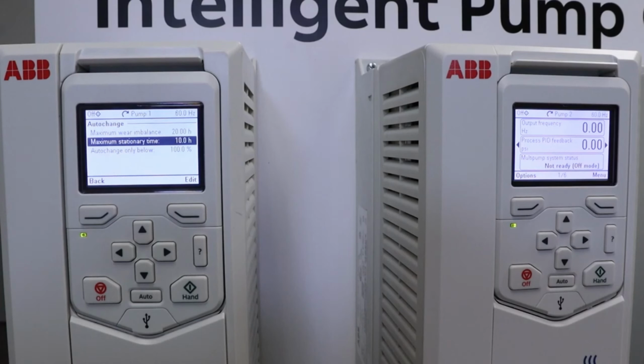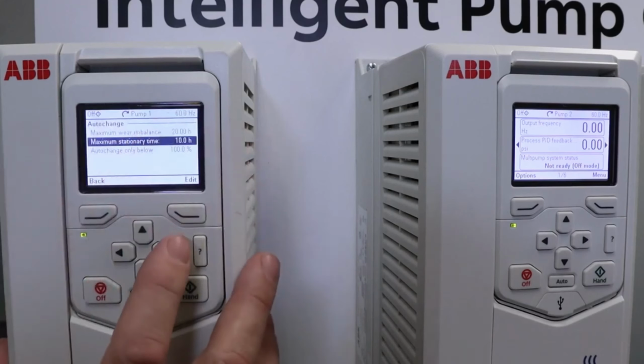That could be adjusted to like 90% or 80%, so when you're in a high demand scenario, you want to make sure you're below that demand when you're doing your auto change. But the auto change in our system actually does smooth auto changing. It will bring up another pump, and it will lower the pumps to even them all out and do the changeover. So, this is the settings you can set.